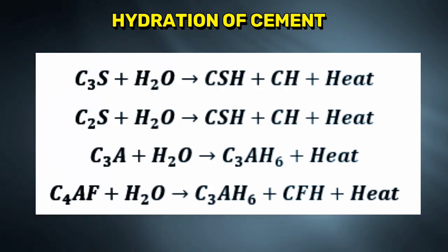It does allow lower kiln temperatures in Portland cement manufacturing, and most Portland cement color effects are actually due to C4AF. So they are due to C4AF, tetracalcium aluminoferrite.